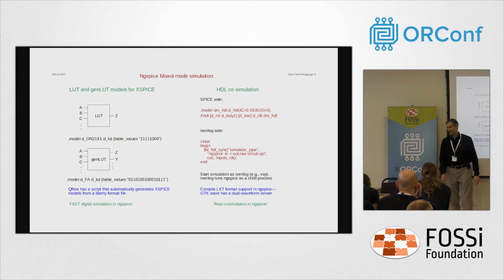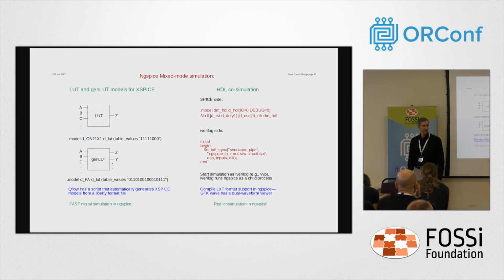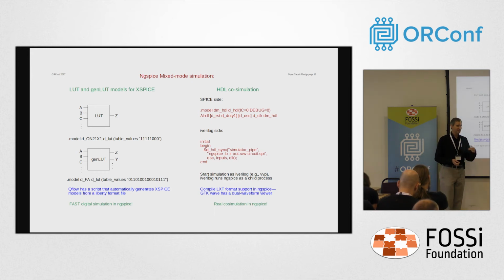There are a few caveats for it. It doesn't always work under all circumstances, but I found it very useful to run it in a way in which I take everything inside my chip. So all the digital there is synthesizable. That all corresponds to real physical stuff. It can all be compiled into XSpice. Outside the chip, you want to drive it with stimulus. That's not physical, so you can do all sorts of things with the Verilog that is non-synthesizable.